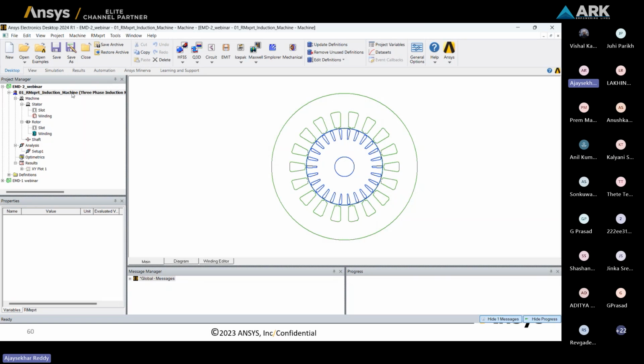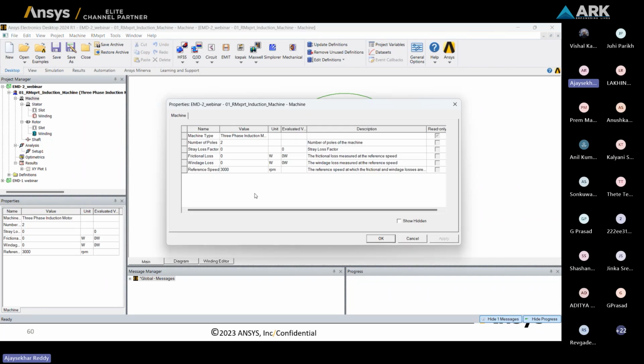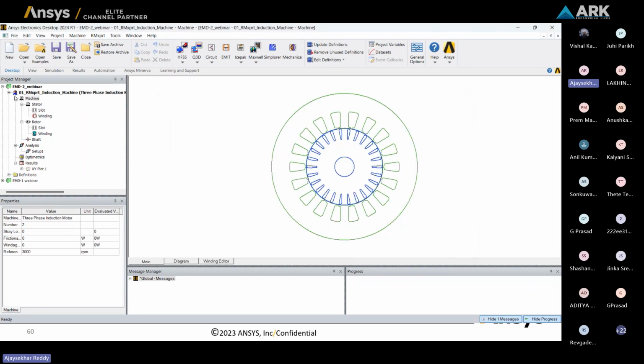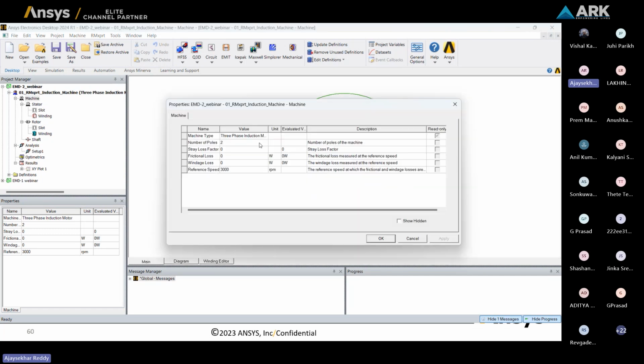With this procedure, you will just open a blank machine, so all the properties or values will not be there. Once the design is inserted here, you just have to go to Machine and enter the parameters like this. The machine which we are going to design now has two poles and works with a 50 Hz frequency. Its power rating is 4 kilowatt mechanical power.